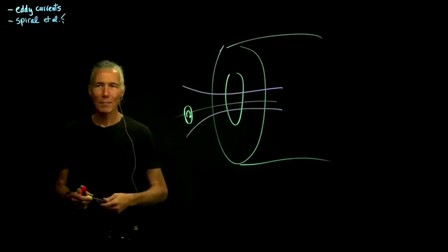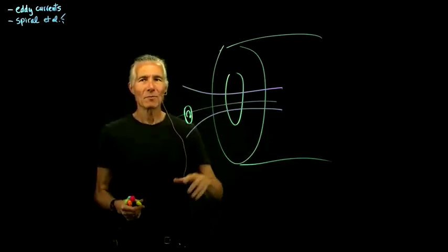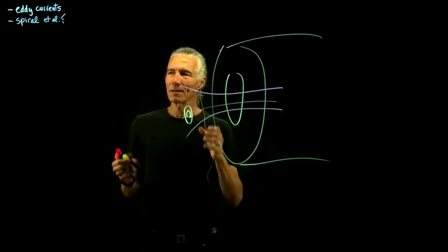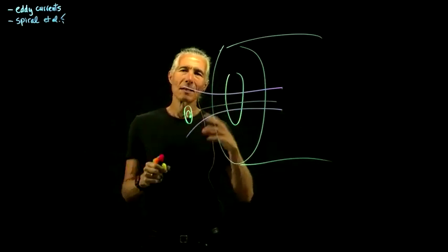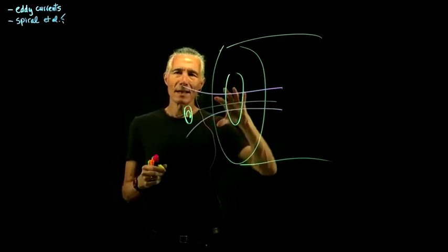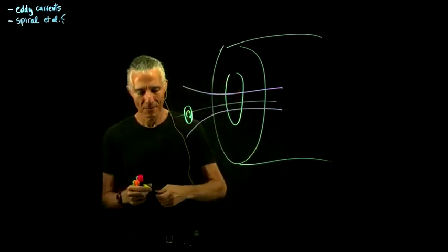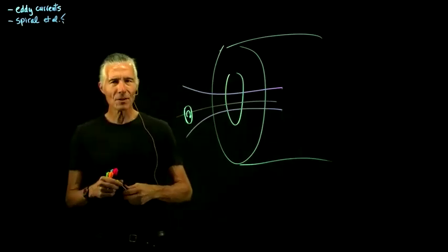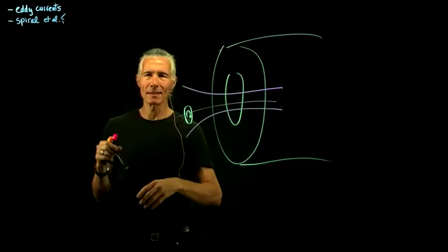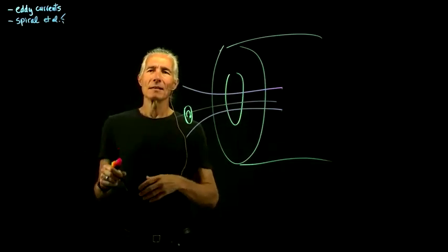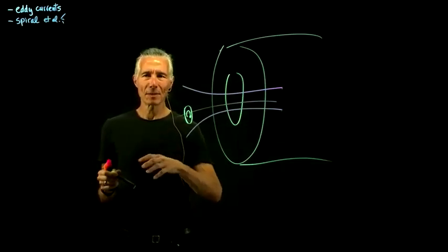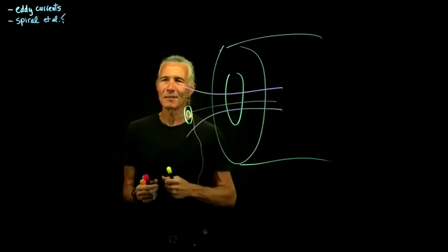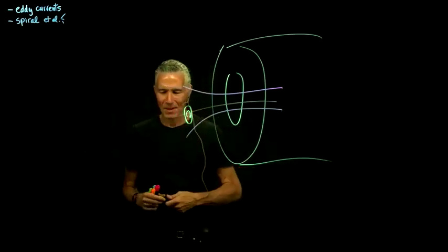So whenever you change the gradient coils, it causes all these currents to slosh around in the actual metal of the magnet, of which there is a lot. The important thing about these currents is that they're long-lived. They take a quarter of a second or something like that to play out, so it's quite a sluggish response.